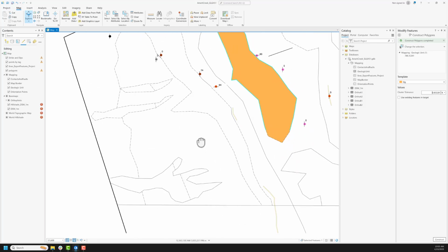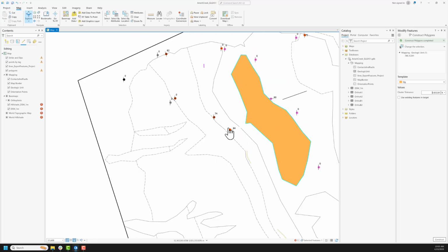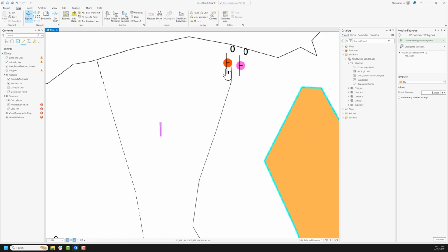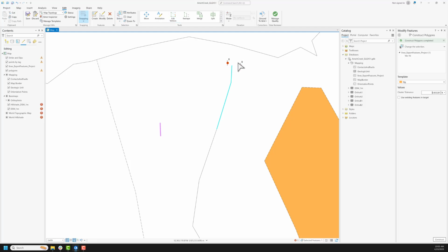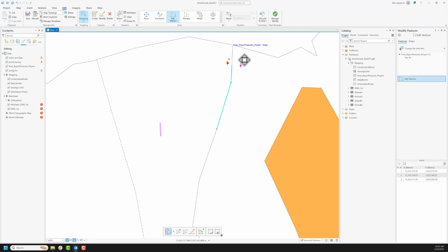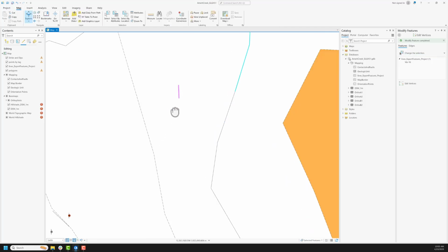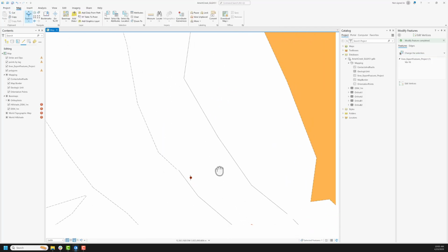And so you just have to go through this one in here, which I know is Dripping Springs. However, you can see already that I've got a problem here. This line doesn't close out. So before we can even attempt it, let's fix that. I select the line, and now I want to edit the vertices. So I need to pull that there. Say check. And let's do a kind of inspection here to hope for minimum gaps.